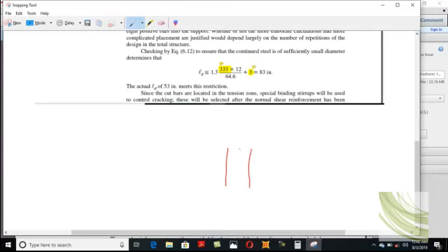Yeah. The beam length is measured from the center line. Clear? This is the center line of support. Okay, this is the center line of support. Clear? Now this 5.30 is measured from this distance. Okay, there is your theoretical cutoff point. This is your theoretical cutoff point. Clear? Okay, it lies a distance of 5.30, and this distance is basically equal to 6 inches or 0.5.